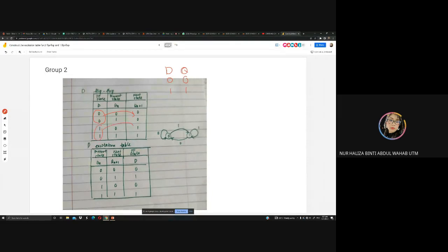That's why for step number 4, it's very easy for D flip-flop. You just copy every single thing at your next state, and you're going to get the value of your D. So the excitation table you can define is supposedly easier, which is D.